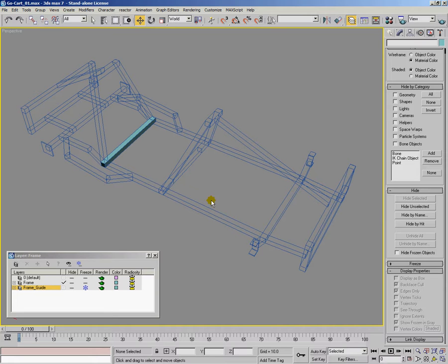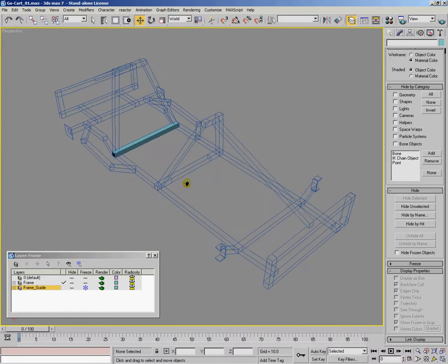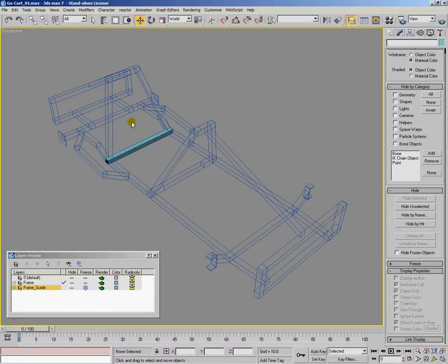create the other side. The easiest tool to use these days is a modifier called symmetry, which, as you can imagine, has been designed specifically to carry out this task. And what it does is it actually effectively cuts the object down a certain plane that you define. Then it mirrors the object based on that plane. And then it welds the vertices together. In other words, it attaches the vertices together so they become one along that plane of symmetry.